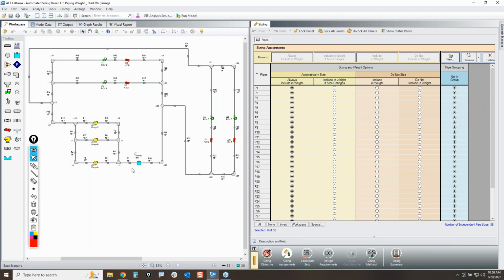groups. So when you want to enforce a level of commonality, for example, I want all of these pipe sizes to be sized, but then I want them to be the same size. That's our common size group. So the way that you create them is you simply click on New to create a new common size group. So I'm going to start off with the main header,